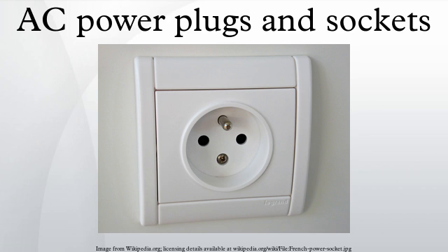It is similar in appearance to the Australasian and Chinese plugs. The pin length is the same as the Chinese version. The most important difference from the Australian plug is that the Argentinian plug is wired with the line and neutral contacts reversed. In Brazil, a very similar plug and socket are still commonly used for high-power appliances like air conditioners, dishwashers, and household ovens. Since Brazil adopted the NBR 14136 standard, which includes a 20A version, the original motivation to use the so-called Argentinian plug has ceased to exist.